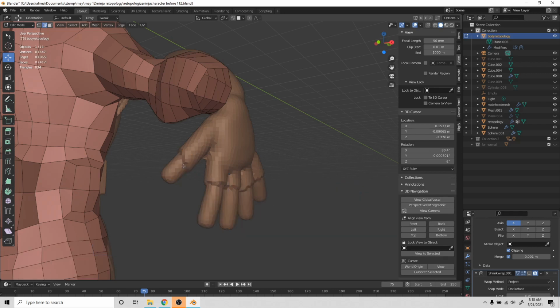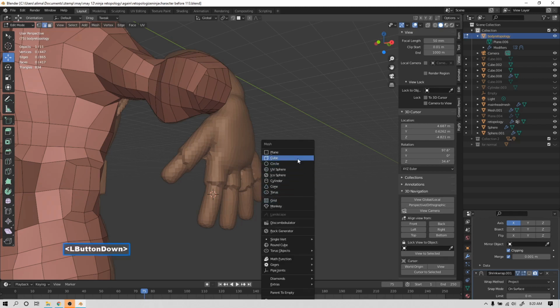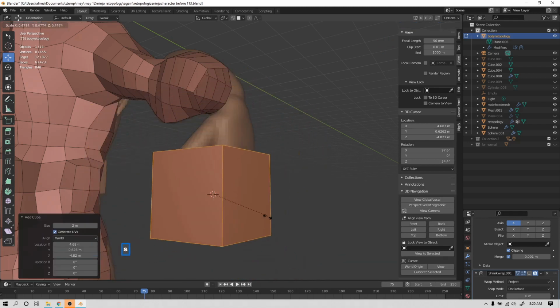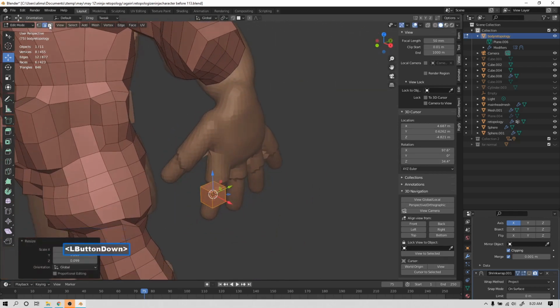So now what I'm going to do is hold Shift, and then right click while holding Shift. That put the 3D cursor there. It's important because where the 3D cursor is in Blender is where objects tend to come into Blender. Okay, so what we're going to do is hold Shift, press A, then bring in a cube. Press S to shrink the cube down. Hold the middle mouse button to rotate, go to the upper left, go to face, select the top of the cube, press X to bring up our delete menu, then choose delete faces.